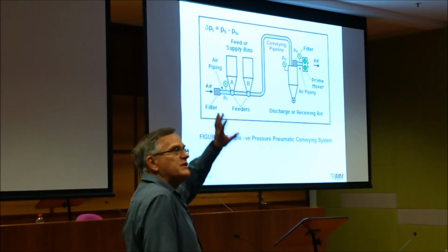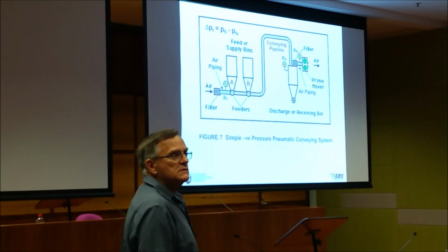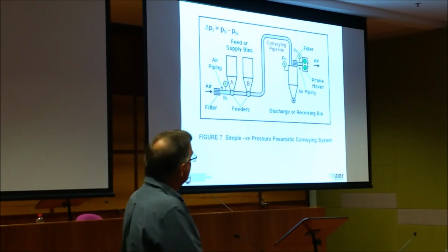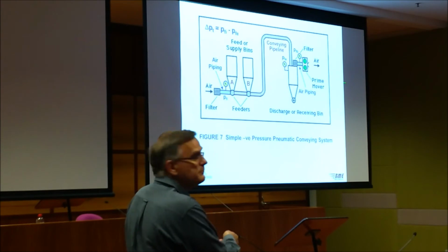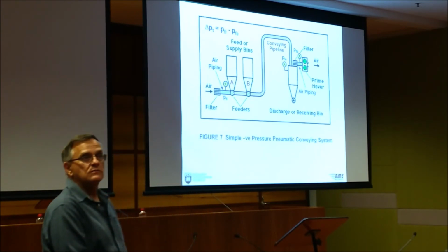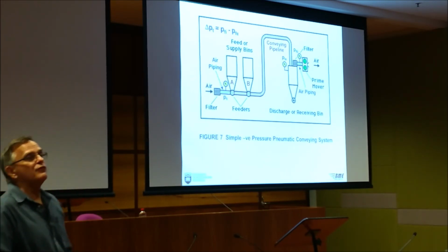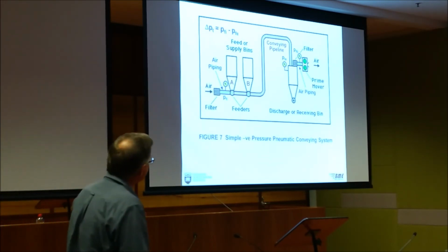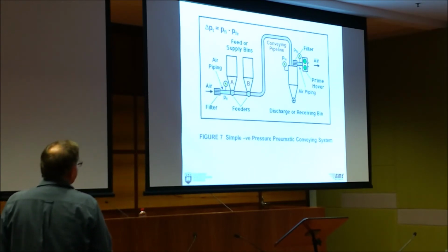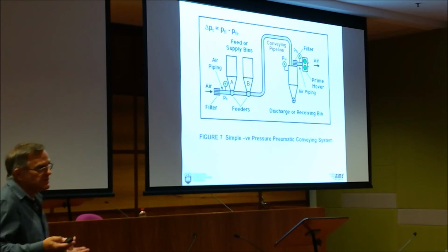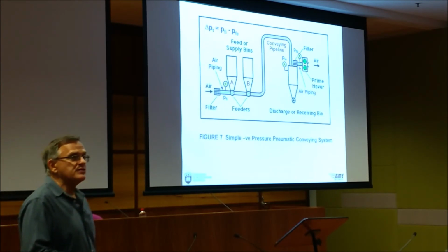And that's the pressure we need to size that blower. Right? Because that's the maximum pressure difference across the blower. So if you ignore that filter loss, you may be out with your blower selection. You've got to make sure you calculate that air piping loss properly and also your filter loss properly. Alright, so as far as the conveying pipeline is concerned, though, it's still PFI minus PFE. It's the same equation. Any questions on that?